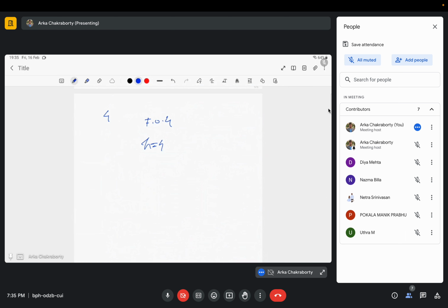Basically what happens, see, I have designed a complex circuit. Okay, my input is this, my output is this, and there is some complex circuit inside this black box. Now I can keep on increasing the W's in the transistor stack. I can increase W in this one, in this one, in this one, or in the black box, and say I've increased it by a factor k. So my resistance R would reduce by a factor k, and my capacitance would increase by a factor k.